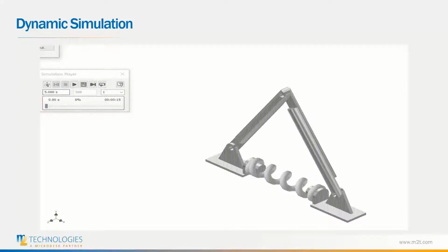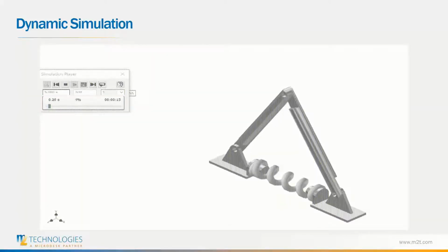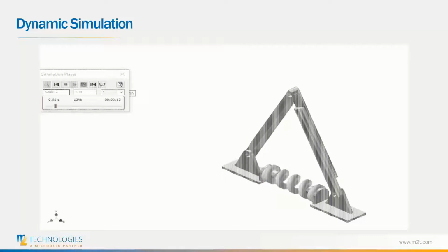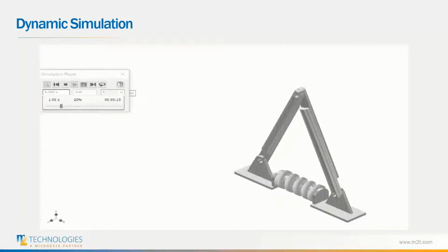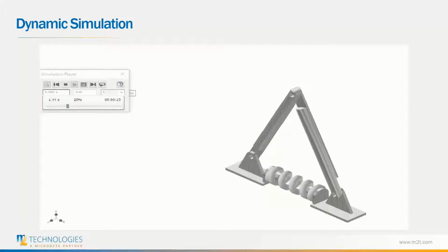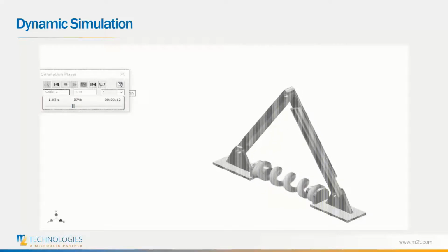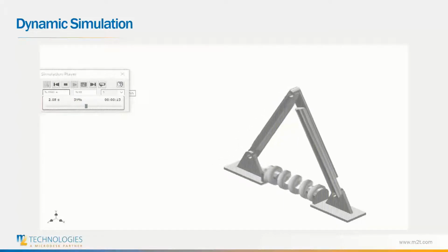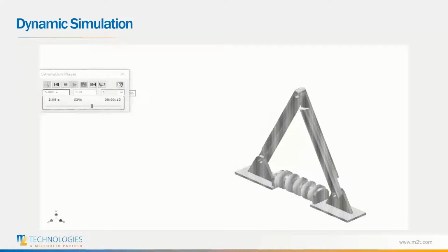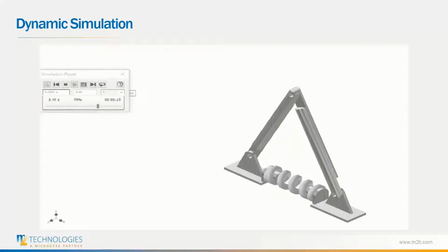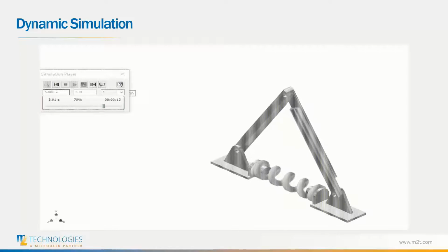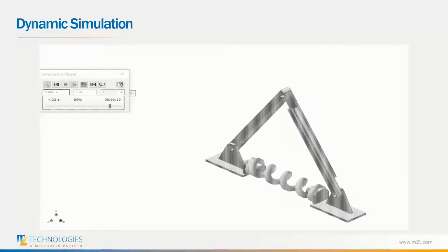Once we apply this, we're able to simulate the motion that will be caused by this force. As we can see here, the simple loading and unloading will compress and decompress the spring. This allows us to quickly determine visuals of how our forces are affecting our assemblies. From here, we can either use a graphing tool to create a graphical representation of this motion or the forces involved, or we can export this to another FEA program in order to simulate the stress caused by this interaction.